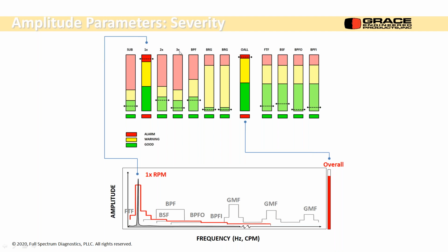So this is 1, 2, and 3 times harmonics. There's subsynchronous, there's blade pass. If you know what the bearing is, you can put those values in and upload just that tight frequency band instead of the whole spectrum. I believe the spectrum's calculated originally, and then if you just filter off different sections, you get all kinds of statistical information on discrete frequencies in the spectrum.